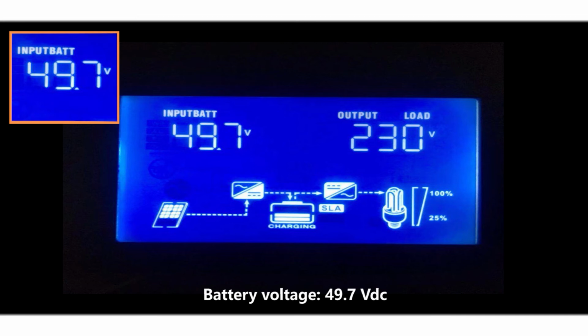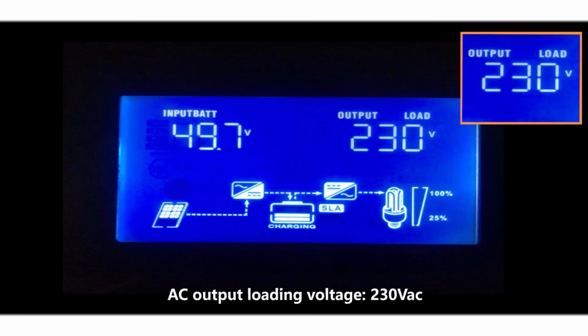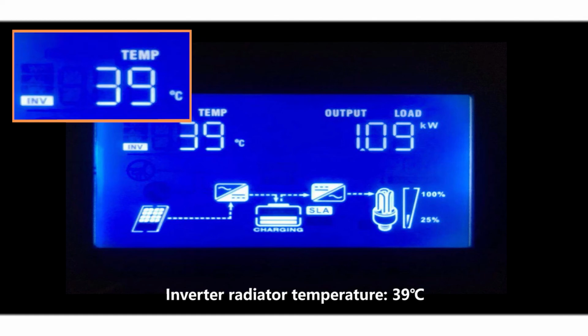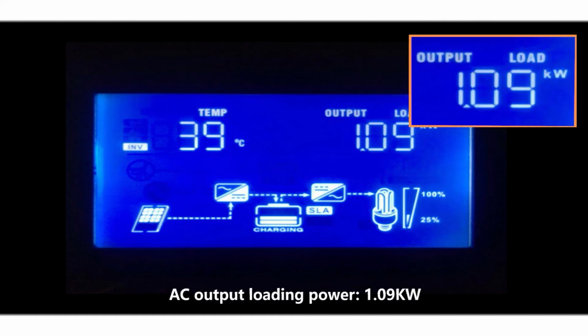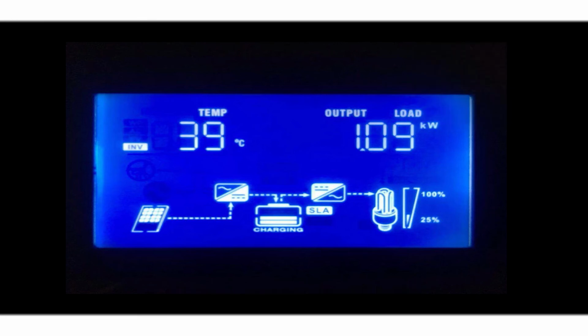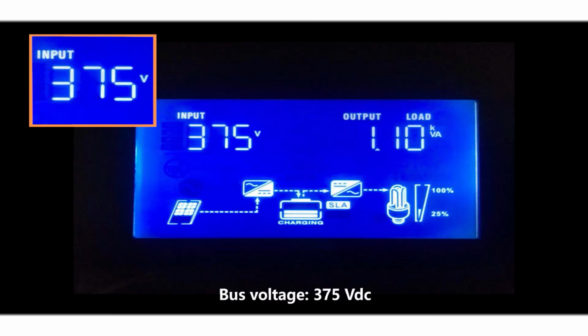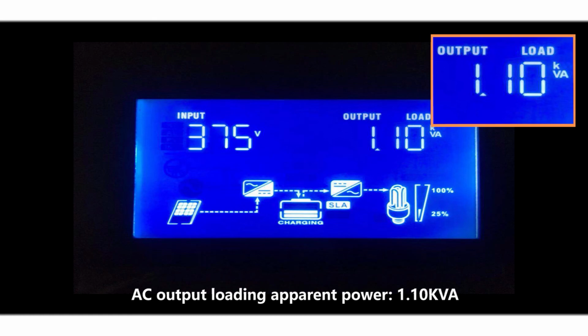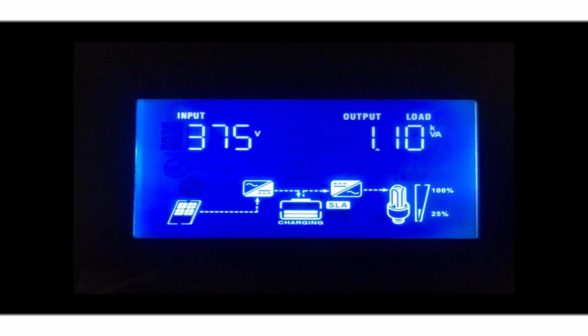Battery voltage 49.7 VDC. AC output loading voltage 230 VAC. Software version number. Inverter radiator temperature 39 degrees. AC output loading power 1.09 kilowatts. Bus voltage 375 VDC. AC output loading apparent power 1.10 kVA.